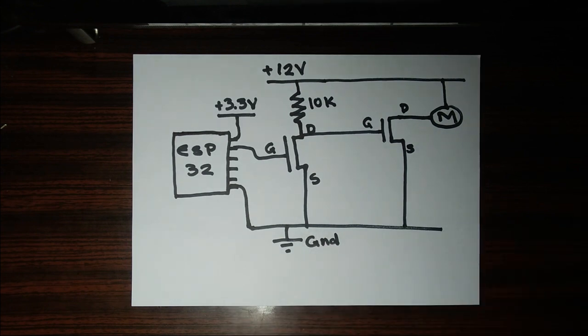We couldn't do this with a CMOS gate, as 3.3 volts would turn on both the P and N parts of our bridge, effectively short-circuiting the positive and negative rails. The problem where you energize both the P and N parts is called shoot-through. We must always pay close attention to this never happening, or our MOSFETs will produce the magic white smoke.